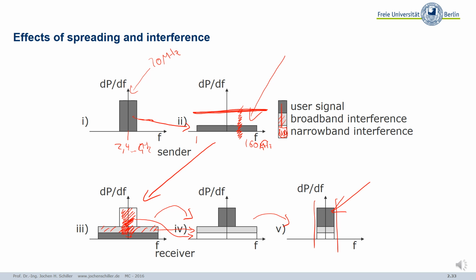And then in addition, if you do not tell anyone how you code your signal, even if you receive the signal, you cannot despread it. So this step of despreading works only if you know the code. If you do not know the code in this step, you cannot despread the original user data. So first, you hide it, and second, you use a secret code.